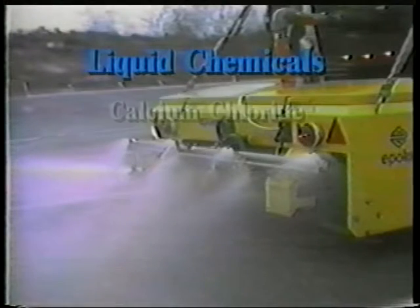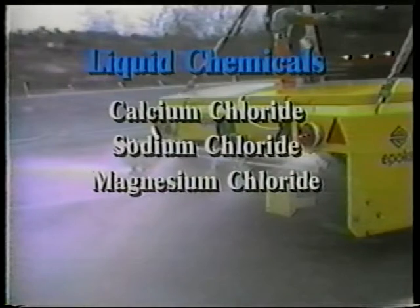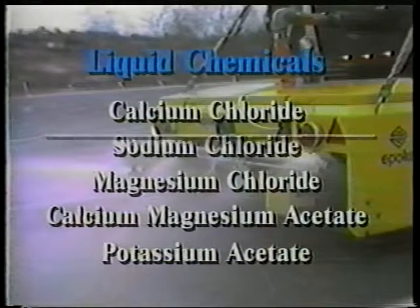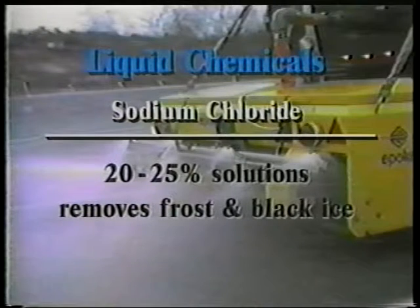Five chemicals: calcium chloride, sodium chloride, magnesium chloride, calcium magnesium acetate, and potassium acetate have all been used in liquid anti-icing treatments. Calcium chloride has been used on some highways at rates down to 65 pounds per lane mile of equivalent solid chemical. 20 to 25% sodium chloride solutions have been shown to be effective for anti-icing and for removing frost and black ice.